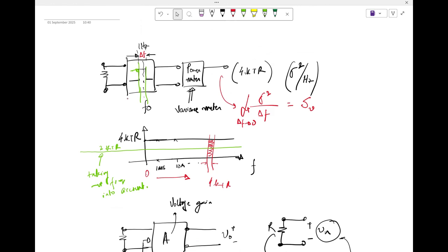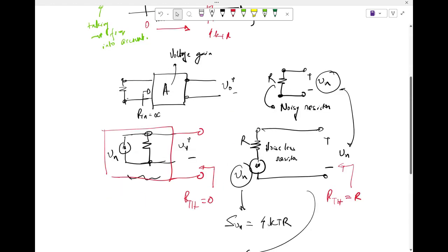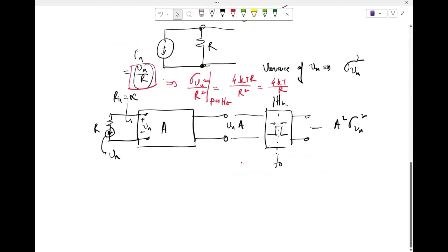The Gaussian term comes because if you check the statistics of it, the amplitude of the noise that you are going to observe over an infinite number of experiments is also Gaussian, right? So hence the term Gaussian. But all of these are used interchangeably: white thermal noise, white Gaussian noise, thermal noise, whatever. Whenever I talk about this in any one of these terms, you should automatically relate that we're talking about these kinds of scenarios.